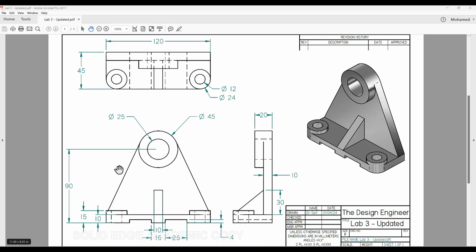In this front plane, I start with a rectangle by center, then get the 2 circles, get the tangent lines, and then work with the details. This is what I will do, and you will see it in my video.